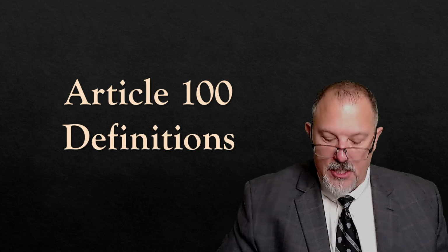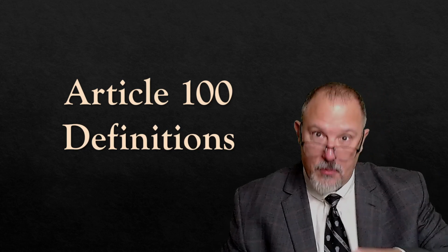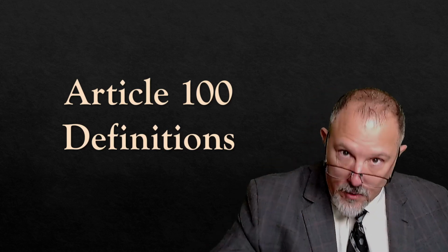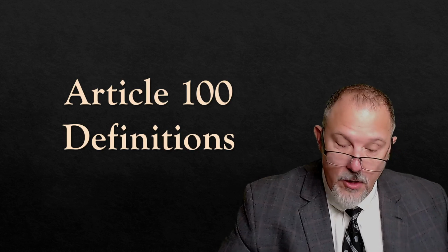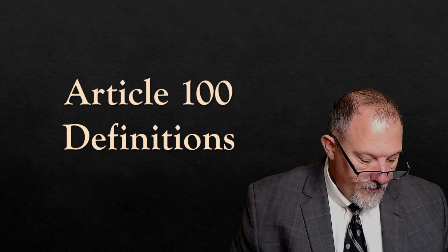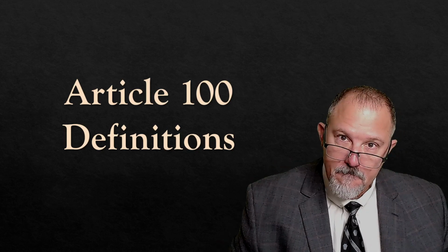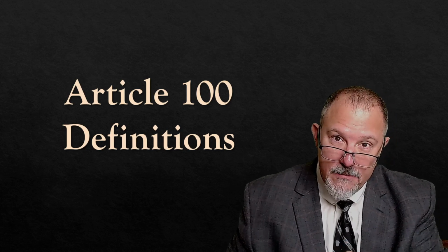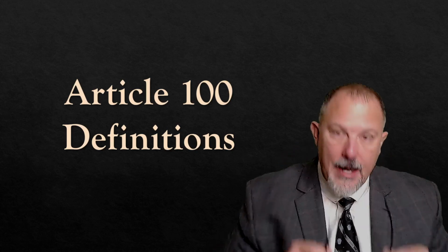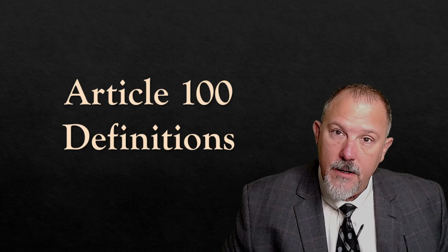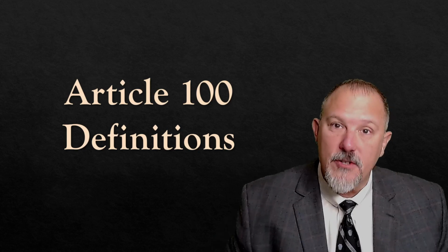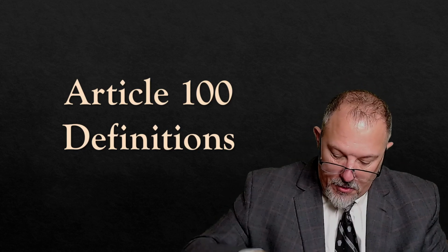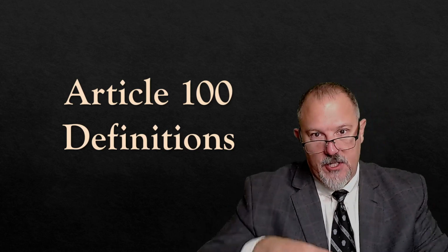Any of those three conditions. So a circuit breaker has to be able to respond to an overcurrent, which could be a short circuit, an overload, or a ground fault. And we're going to understand how it does that. And we're going to understand how we determine how long it will take for a circuit breaker to open based upon an overcurrent.